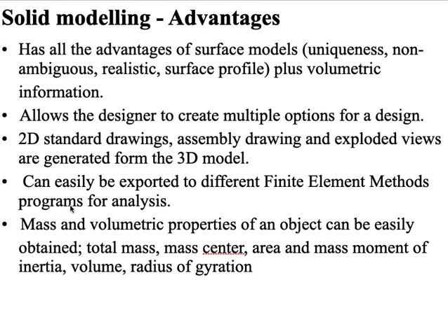Looking at the advantages of solid modeling, it has all the advantages of a surface model, that is uniqueness, non-ambiguity, and elastic surface profile, plus volumetric information, and it allows the designer to create multiple options for a design. 2D standard drawings, assembly drawings, and exploded views are generated from the 3D models as well, and it can easily be exported to different finite element method programs for analysis.